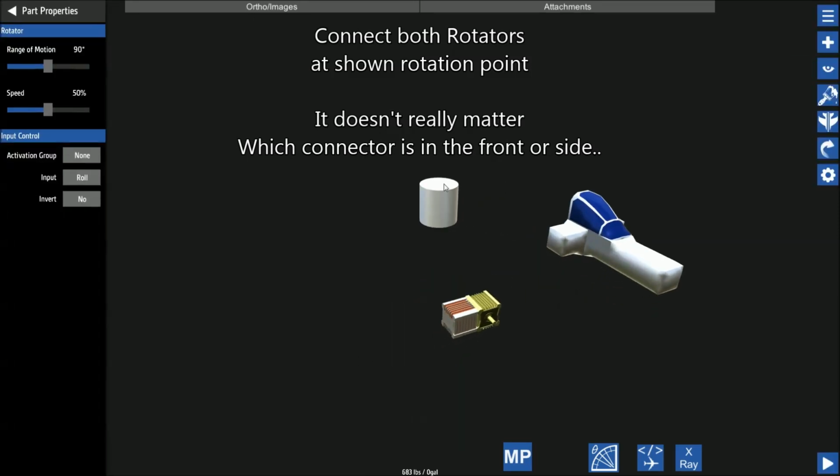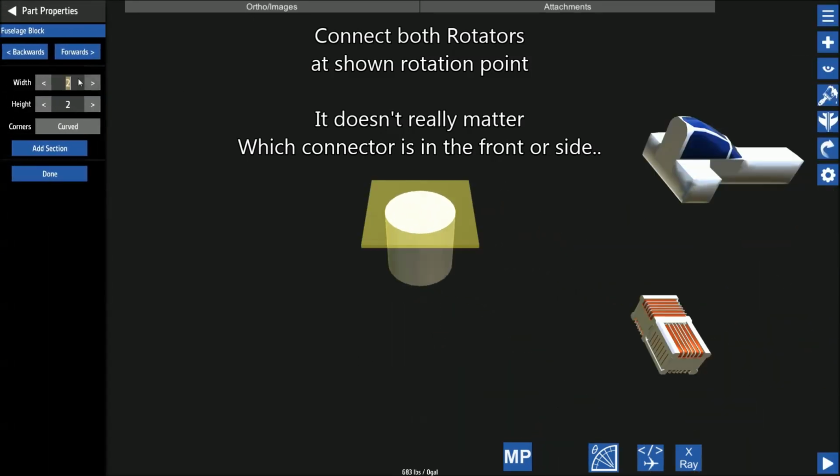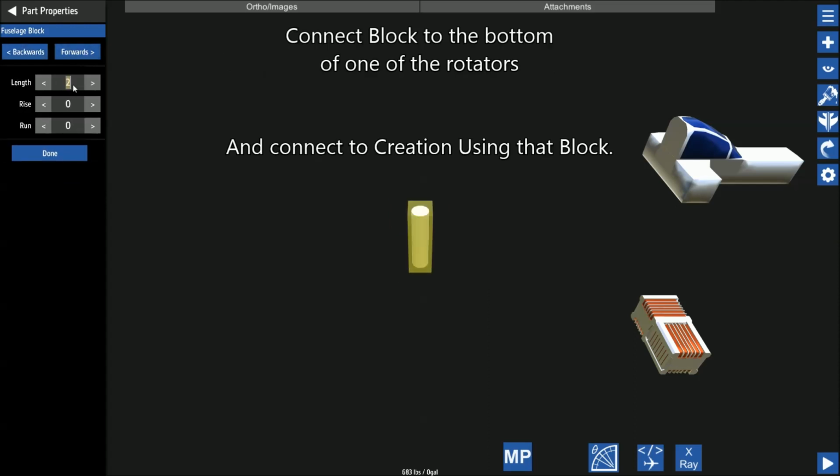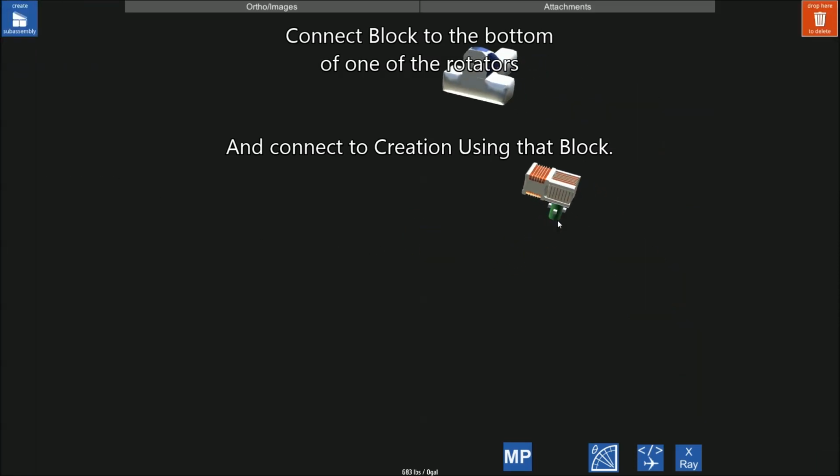I connect them outside. It's going to make stuff easier, and then I connect it as a unit from whichever block I choose, basically. So now this block that I'm editing is gonna be the anchor block to the whole joystick. So whenever I want to move it or move the entire thing, I just select this block and move it with all connected parts using the transform editor, basically.